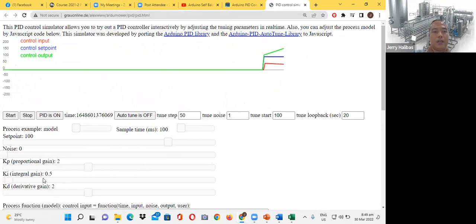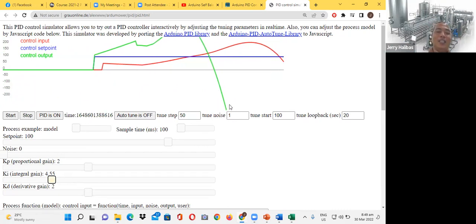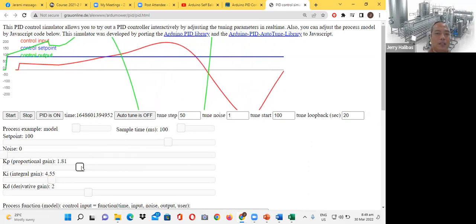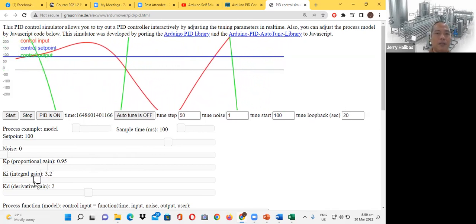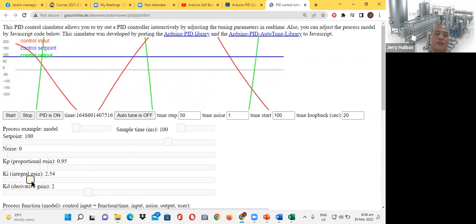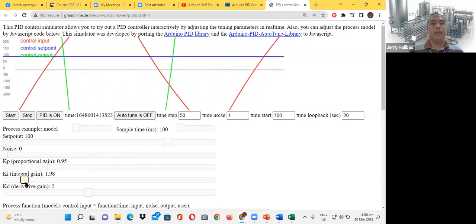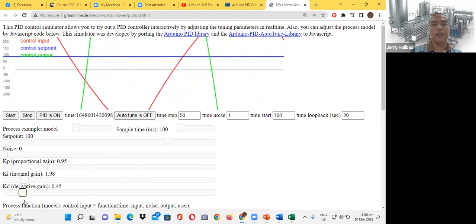What if you add derivative and integral, what is the effect? When the integral is increased, it has this effect. Once the integral is too high, that overrides the proportional. But let's try when the proportional is 1. Now it overshoots. It depends on the process that was set, and different processes have different responses. Okay? And so on and so forth. The derivative gain is also large.